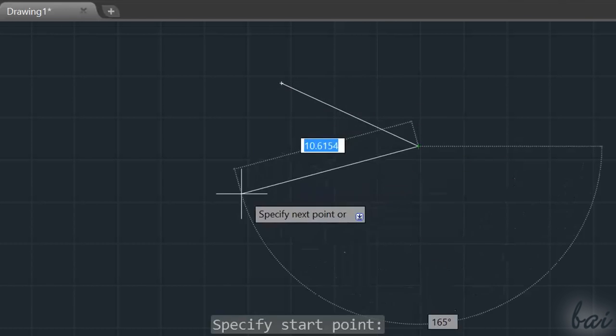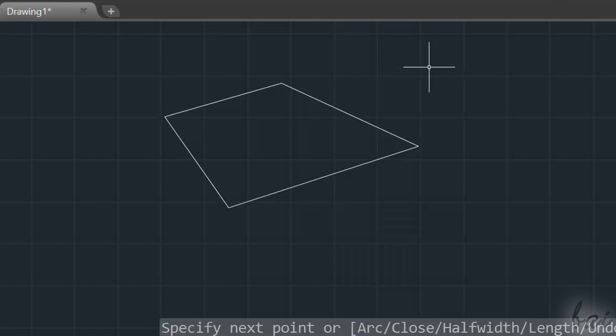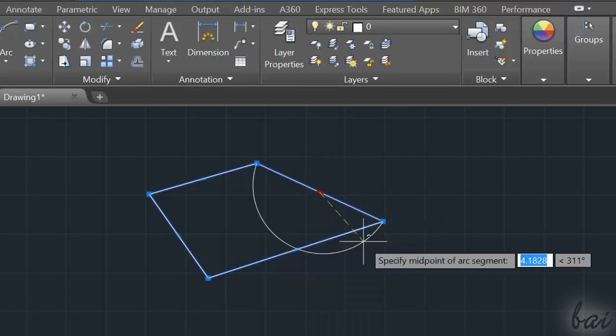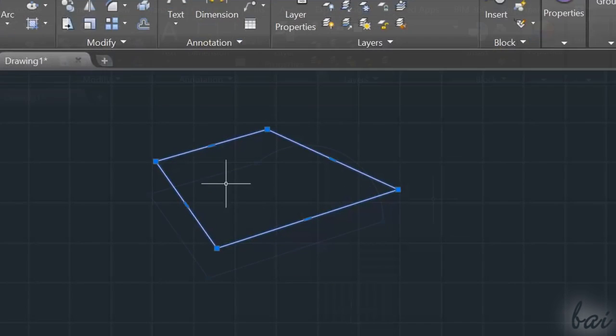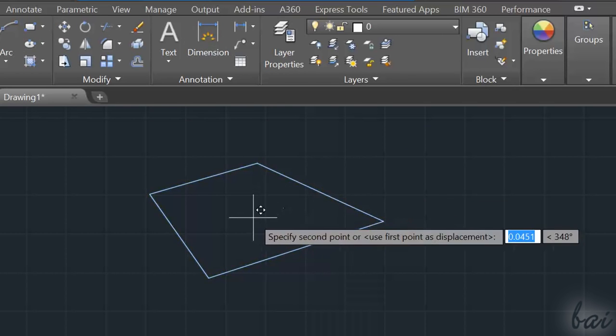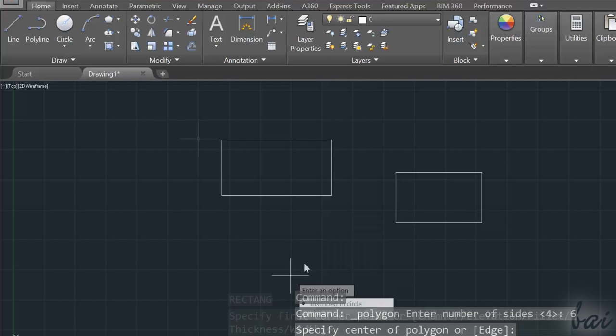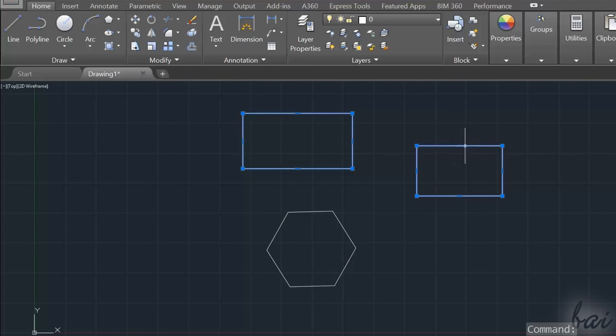Unlike lines, polylines are used to create curves and polygons. In fact, if you draw a closed path, it is built in one piece. And if you select the polyline, it shows smaller nodes that you can use to turn sides into curves through Convert to Arc. You won't have any node used to move, so in these cases you have to use the Move command. When using the rectangle and the polygon tools, you will simply draw polylines with a regular shape, so nothing different from the objects created with the polyline tool.